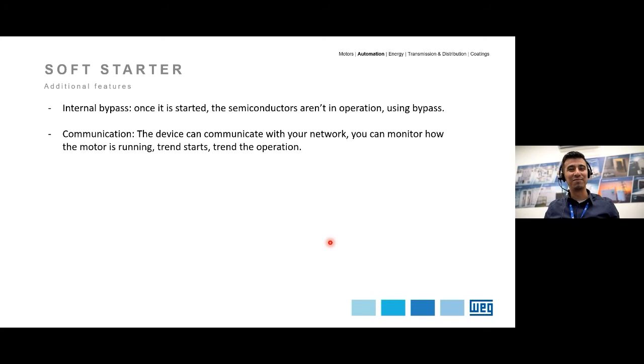And for the geeks, the SSW 900 also does carry a PLC internally, right? So what you can do, you can start decentralizing things and putting small software on your starter. So you can keep one PLC on your DCS, for example, and then start placing different software elsewhere on your site, decentralizing things as well. Okay, it's a very good feature of the SSW 900.